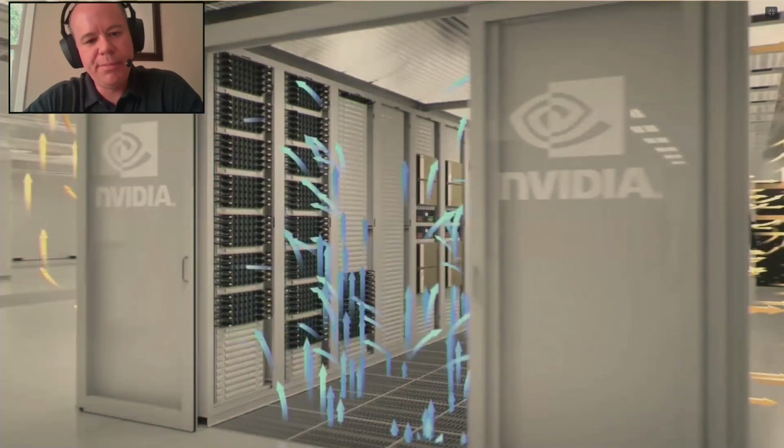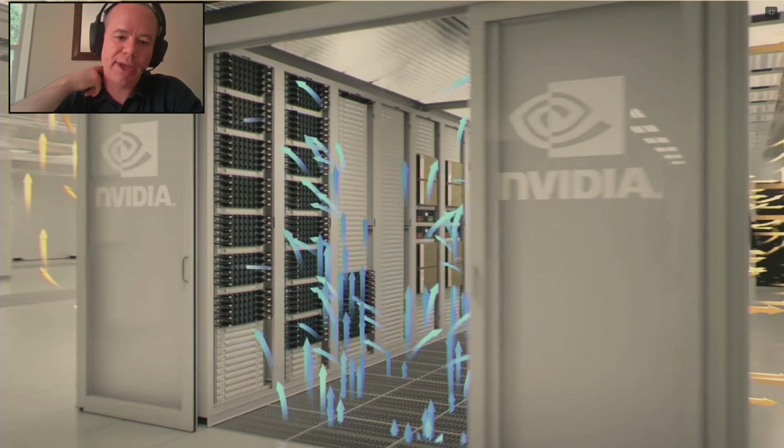So here's a picture. This is a snap out of the video that's released on YouTube on how we handle cold aisle containment. But most simply, we have perf tiles in the floor, and the perforated tiles allow the air to come up. So the machines see cold air first, which reduces a lot of pressure on keeping the whole data center cooled to get maximum performance out of the system. So this is a very easily deployable design, and we have multiple people that replicate and deploy this design.